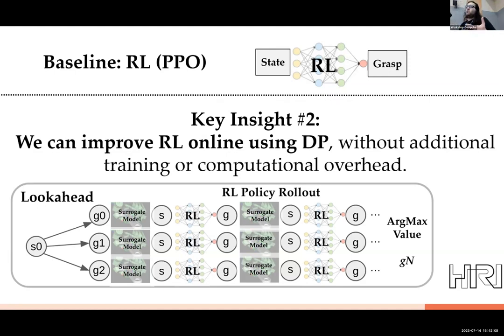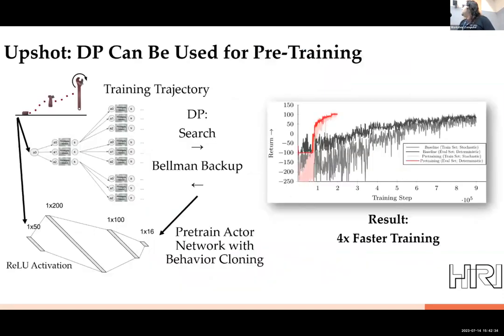So the main contribution of this work is that since we have designed this contact controller and we know the dynamics of that controller pretty well, we can use those dynamics at test time, parameterized by the test time dynamics of the system, to take whatever RL policy we learned offline and improve it online without any additional training steps. You can think of this as a one-step policy improvement that can happen online to handle changes to the environment.